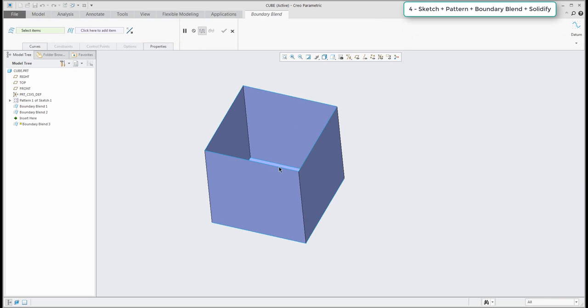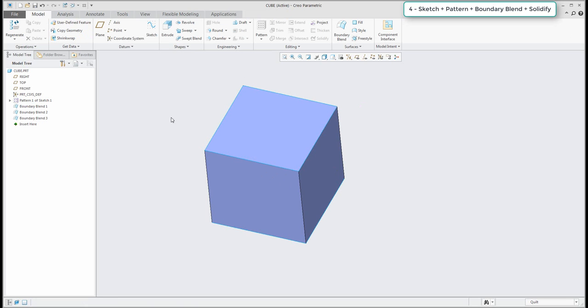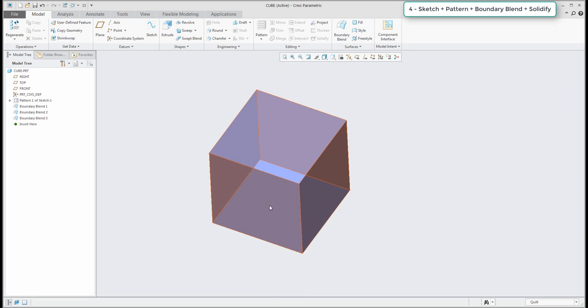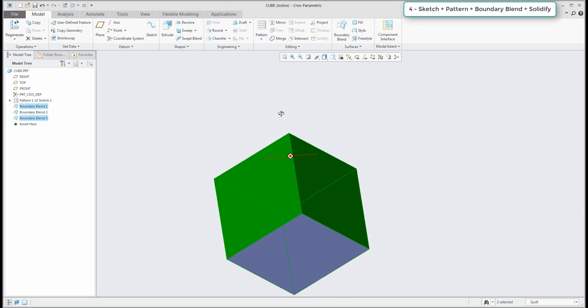So create a boundary, select right and left. The system will select the first curve, control button, and right, left. But what now? You can have a look here that we have 3 different quilts. So I will select filter quilts and I will continue and select the control button. And you can see here that the system automatically recognizes that I can use the merge.